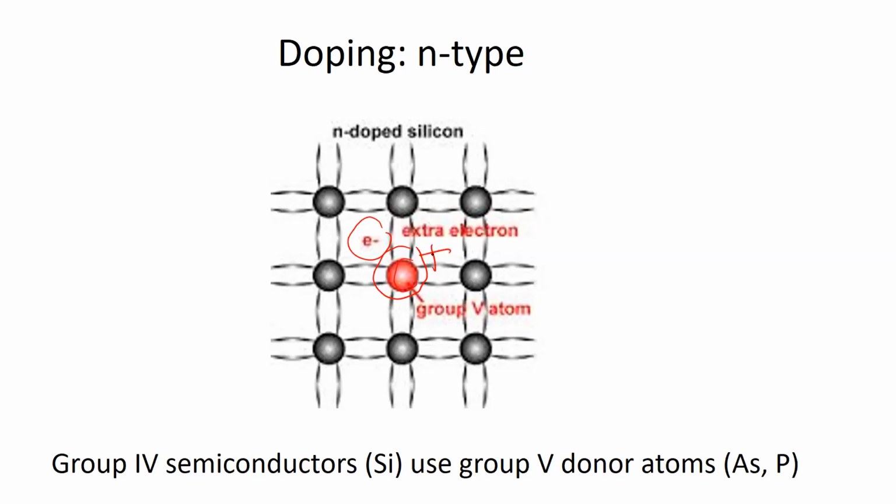And this is important because unlike mobile conducting electrons, these arsenic ions are stationary. Now, excess electrons are generated from the donor atoms, and so we call the donor atoms donors for short. And the concentration of donors introduced is usually referred to as ND, that's N subscript little d. Again, it's measured in cubic centimetres.